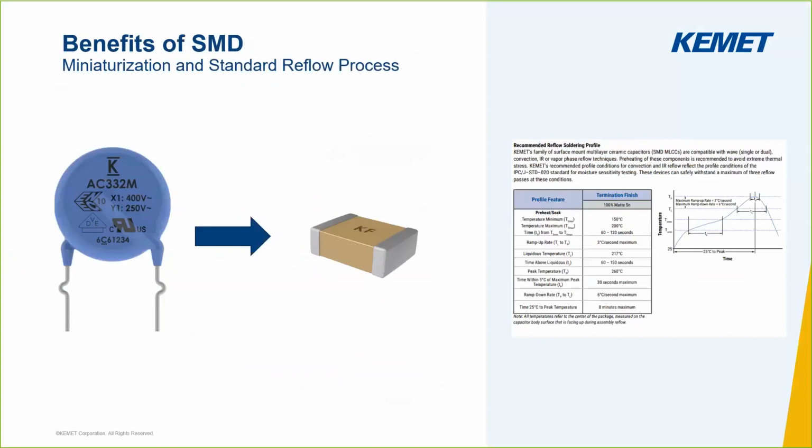So the major push to move to MLCCs back in the 80s and 90s was about smaller form factors, as small as possible in high density applications. And the same thing here is happening to safety rated capacitors. When you have bulky disk capacitors, you can now move and go to that miniaturization trend that everybody desires, and also avoid having two different reflow types, or processes, that you have to go through.